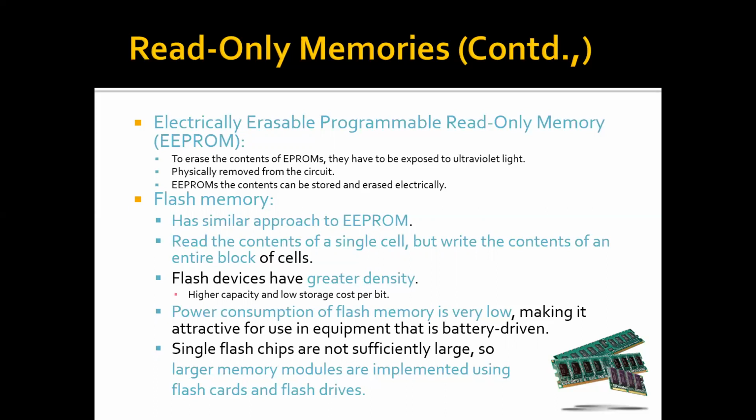One more thing I want to say about the EEPROM is that we require 3 different voltages for read, write and erase. But in flash memory, we may not require 3 different voltages. Flash devices have greater density, higher capacity and low storage cost per bit. Power consumption of flash memory is very low, making it attractive for use in equipment that is battery driven.